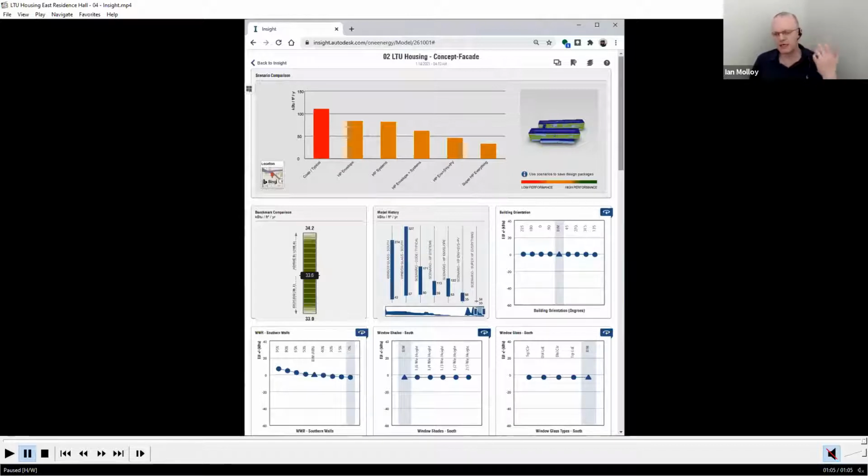At the end of the day, energy use intensity, you know, 2 decimal places. Anything beyond that can't really be measured. What it's really trying to show you is the relative sensitivity of things. So you'll see, for example, the law of diminishing returns with how much insulation you add to the building and so on.